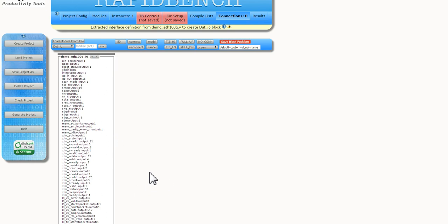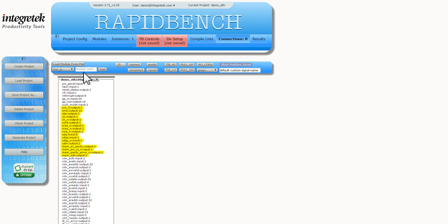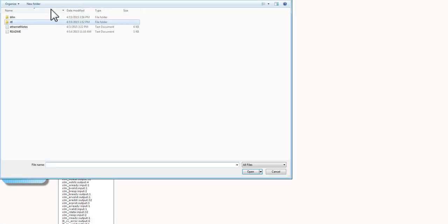Quite a large design. So the first thing we're going to do is try to hook up the DDR3 interface. Now the matching number up there works pretty well when the number is low for shorter names. So since the DDR3 has shorter names, we're going to reduce it a little bit. First, select by clicking the left mouse button and dragging over the signals that we need. And then we're going to simply go and load a user BFM from our system.